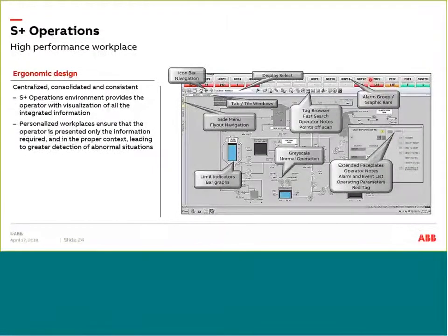So if I click on system, I can see a graphic associated with the entire system. The number below that shows me the number of alarms in that alarm list, graphic, or trend that I'm looking at. Here it's showing 1 and it's green. That means I have 1 alarm in the system, and the highest priority alarm in that alarm list is a priority 3 alarm, because right now I'm saying 3 is green, priority 2 is orange, and priority 1 is red.